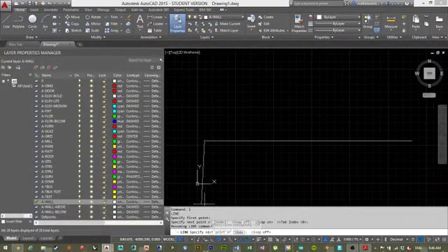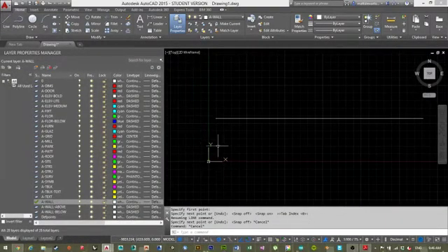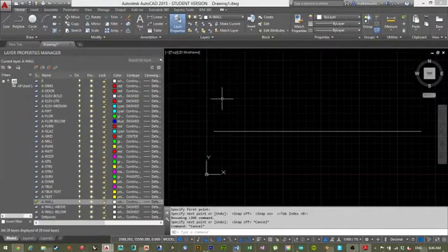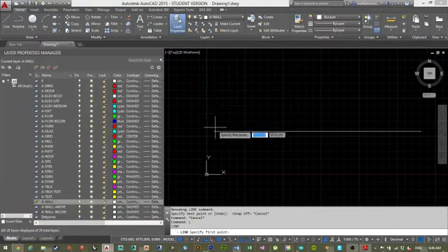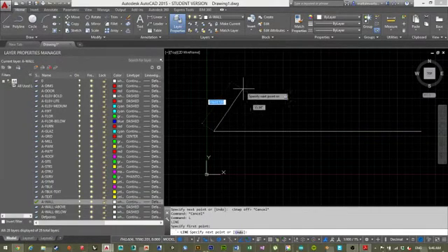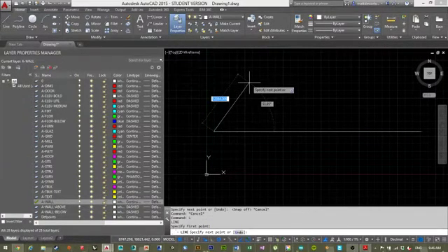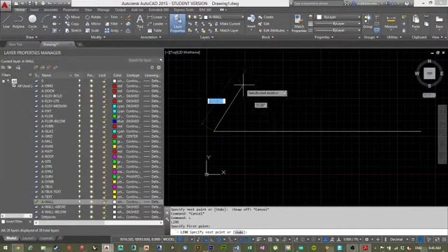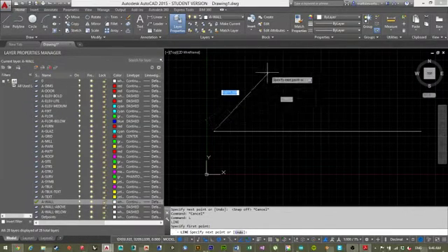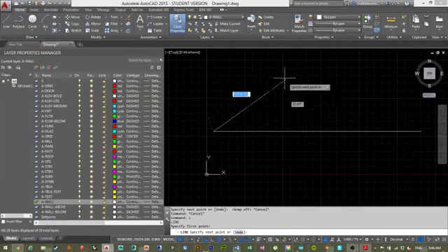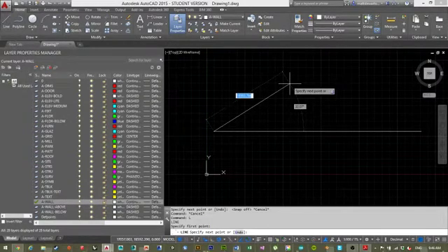Again, a lot of these I don't really use, but I think this is on by default, dynamic input. You'll see if I turn it on and go to draw a line, so I'm just pressing L, from here, you'll see that all those options are up on my mouse, so it's showing the length and I guess the angle between this other line.